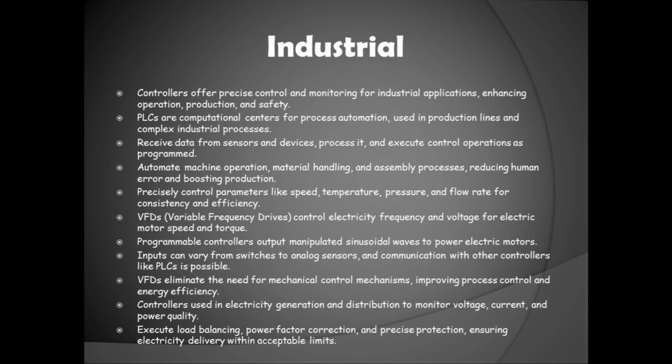Another prominent application for controllers in industrial environments is the VFD, or variable frequency drive. VFDs, also referred to as adjustable frequency drives or inverters, control the frequency and voltage of the electricity that is provided to electric motors to control their speed and torque.